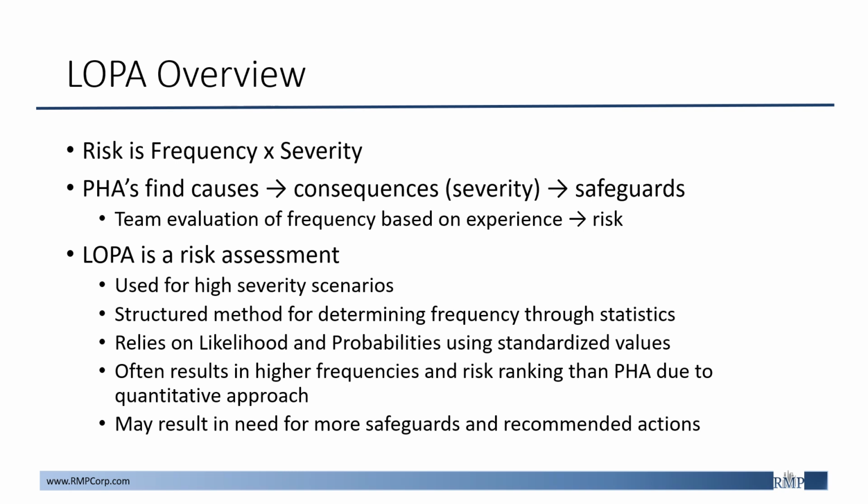The evaluation for this frequency is then based off of experience, which will determine the final overall risk. So what is the probability of a valve to fail, considering a worst case consequence, assuming that all of our safeguards in place are working? Based off of experience, what do we think that overall frequency will be? And that is normally how we determine the frequency and overall risk during a HAZOP.